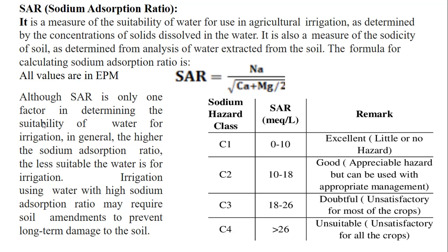And also, a high sodium adsorption ratio will decrease the soil moisture, or it will lead to soil moisture loss, and it will decrease the tilth. This will also lead to a decrease in infiltration and permeability of the soil, leading to problems for the crop or crop generation.